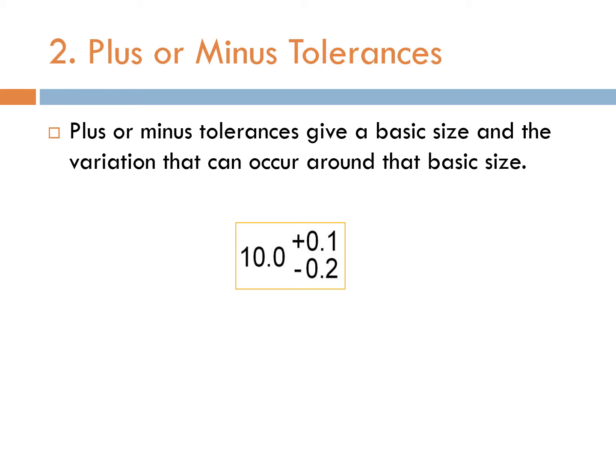And you can also use the plus minus. If you use plus minus, then the plus value means you can go over the first value, which is the actual value that you desired. And the second, bottom value will be the minimum value, smaller than the standard size value. This standard size also has a terminology called the basic size. And remember, it is called the basic size because we are going to use this terminology in the future table.